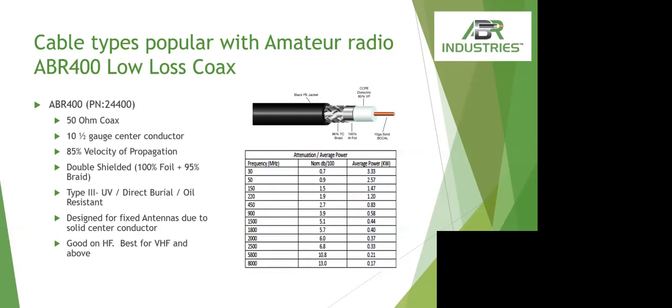But with that larger center conductor, you have to buy a PL259 or an N-type connector that is slightly larger for this type of cable. It's still very common, much more common actually since the 1990s. The nice thing about this product is it's great for stationary antennas, if you're putting up any type of antenna that's sitting there without any movement in the wind. Now I would caution people, dipole antennas, yes, are stationary antennas, but do have a tendency of shifting in the wind as things move.